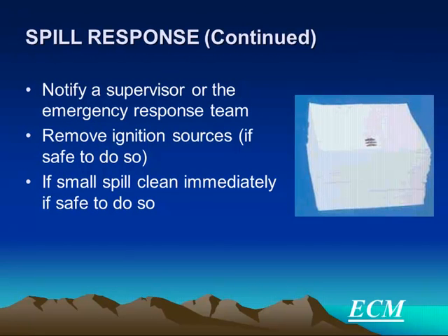If you are going to clean a spill up, notify somebody in case you are injured cleaning up the spill. And if it's safe to do so, remove ignition sources. So if a drum tips over by your lift, go over to the circuit box and shut off the circuit breaker for your above ground lift. You don't want electrical sources when you have a petroleum product